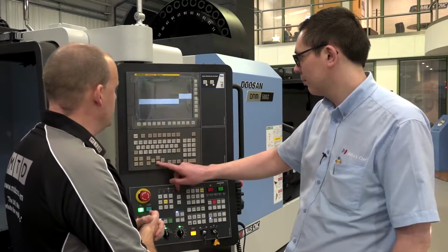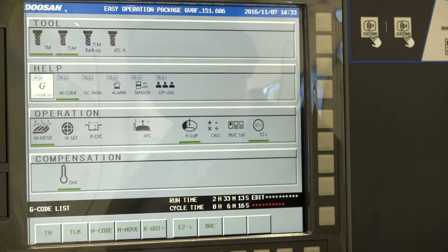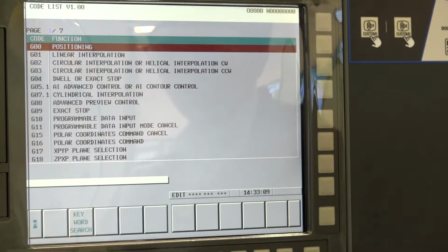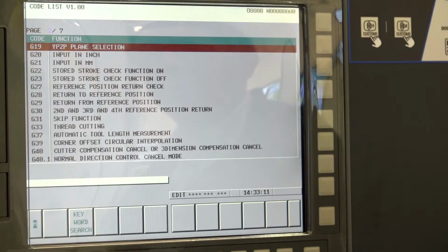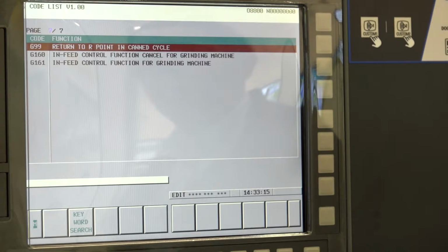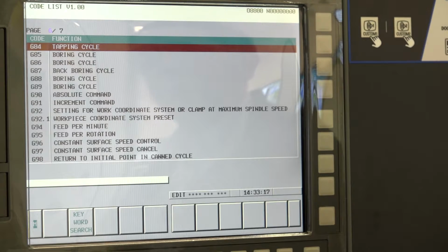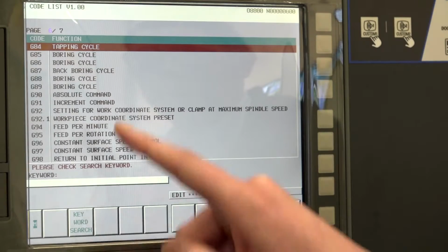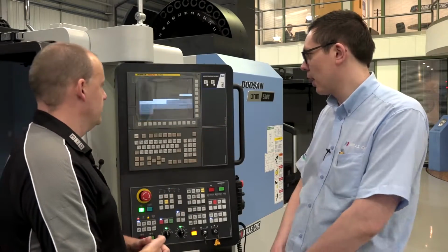Let's go down one then to the G code and the M codes. Okay, G code, M code list. If you're working on a lathe and then you come onto the mill, G codes and M codes are typically different. Just a refresher. So if you were using a lathe in the morning and then you came across the program in the afternoon, you don't want to take a G code from there and put it into this machine because you can have an accident. Correct. That's the same with the M codes as well, I assume. Same with the M codes.